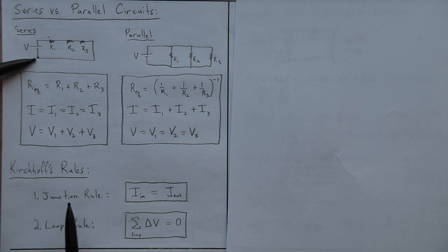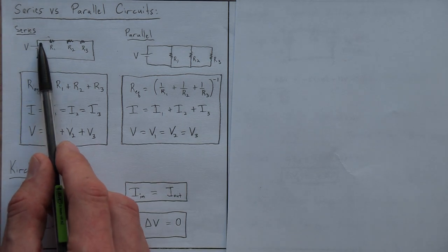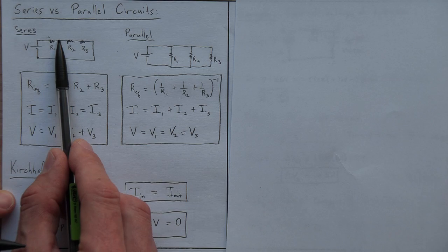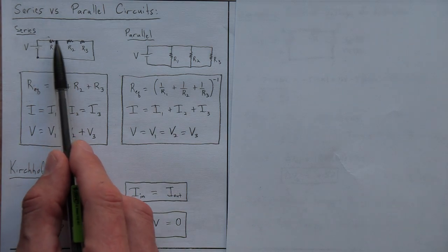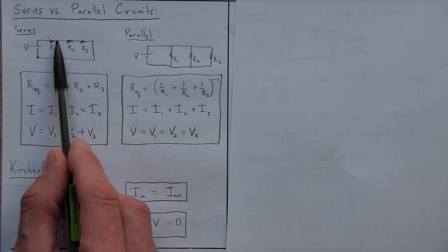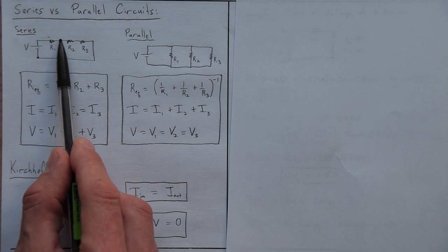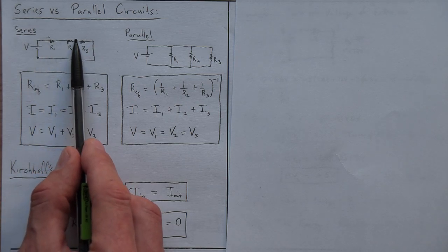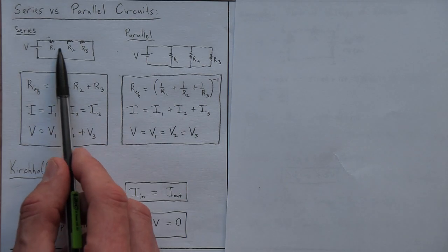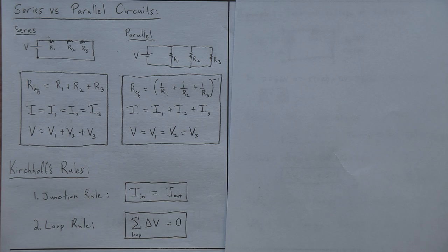So the little ant goes plus whatever the voltage of the battery is, then goes through each resistor measuring IR, but in the downstream direction. If the ant is walking with the current, then it's going to lower voltage, just like water flows downhill. So minus IR, minus IR, minus IR. Plus V, minus V, minus V, minus V. Or you could move all the negative V's to the other side and get this expression right there.